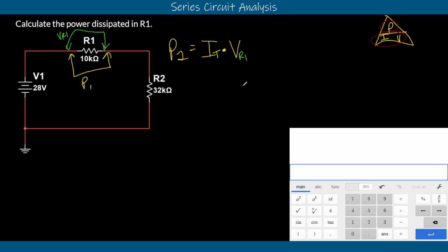So we can do this using the voltage divider equation, and then we can actually solve for power. We can say that power is equal to voltage times current. And if we don't know current, we can break that down again. And we can say, well, Ohm's law says that the current is equal to our voltage divided by our resistor. So when we solve out for that and reduce it, we get a power law that says that the voltage squared divided by the resistor is going to equal the power.